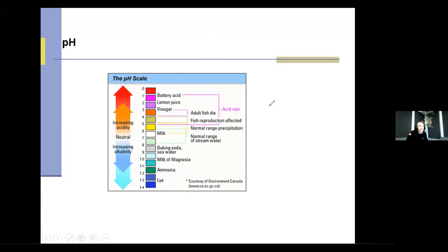But pH for us, to make sure that everything's going to work well, should be 5 to 7. So we need to be in this range here for coagulation to make sure it works well, or works the best.